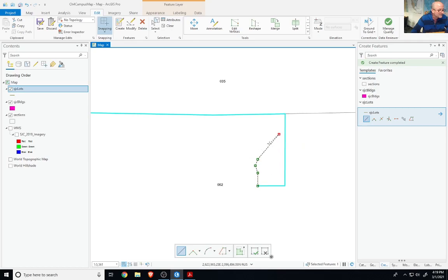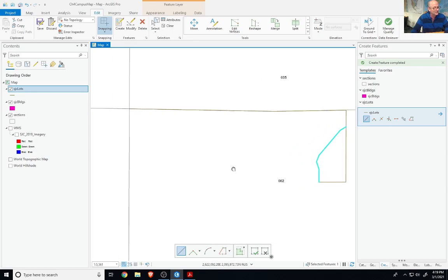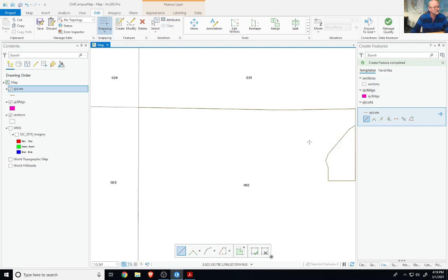Likewise, I've drawn these edges here, and then I'm just going to look for the snap here and close that up, and then F2. So those will be aligned. Notice it selects the series of lines that you had drawn in sequence. So you can easily clear that selection, and you're still in the drawing tool. So I'm going to start back up here and then draw around.